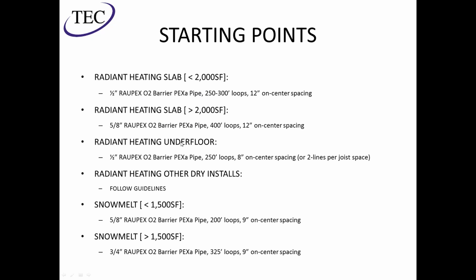When you're doing underfloor heating or joist space, you're looking at 8-inch typically. And then with joist space, we also recommend keeping the loops just a little shorter because you're going to have to leave a little room for tails as you're running back and forth through the joists.